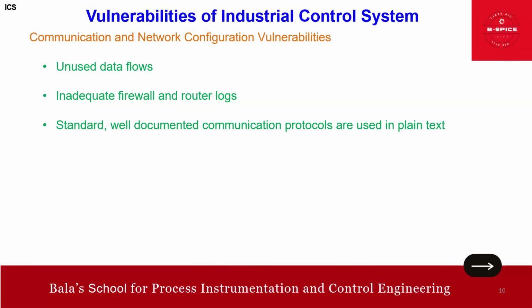The challenge here, since these protocols do not employ encryption, the data transmitted is easily readable by anyone monitoring the network. Thereby, this exposes sensitive information, including the login credentials and commands sent between devices, potentially leading to unauthorized access and manipulation of the ICS network. So this point also we need to take note.